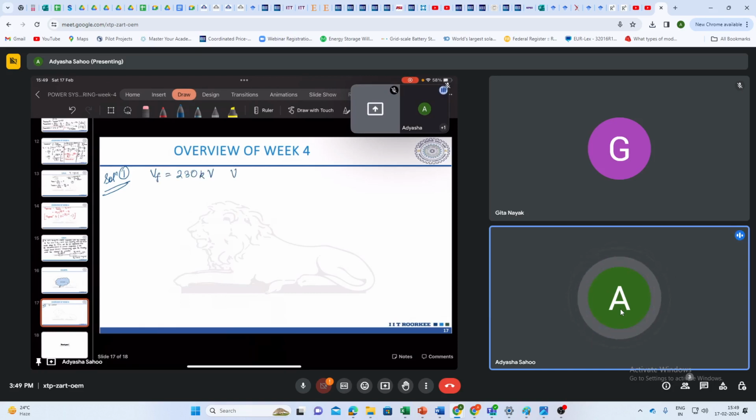So I need to calculate V transmitted. That is 2E times Z surge of the line plus ZL, multiplied by ZL. Instead of ZL we have a parallel combination of line impedances ZS1 and ZS2, so ZL is ZS1 ZS2 divided by ZS1 plus ZS2.